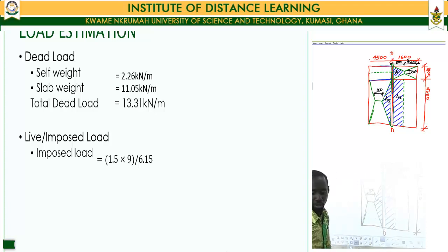So now moving ahead to calculate the areas of the various parts of the slab that the beam is supposed to carry, we now start with area 1. Area 1 has a trapezoidal shape.